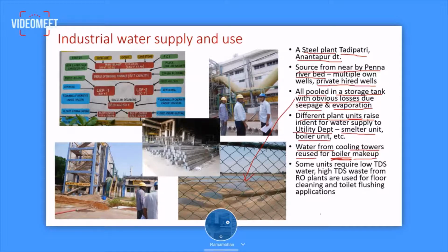At the same time, in the case of a boiler, when you are supplying water to it, it has to be of very low TDS by water quality standards. Ideally the TDS level should be between 0 and 10. Only then is it suitable for boiler application, because if the water is heated up, salts like calcium and magnesium carbonates and bicarbonates precipitate and form white-colored scales within the boiler, and over a period of time the boiler's life is affected and its function goes defunct. So to avoid such situations and extend the life and efficiency of boilers, low TDS water is always supplied.